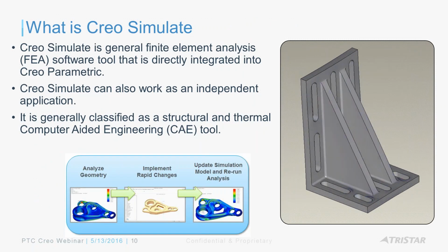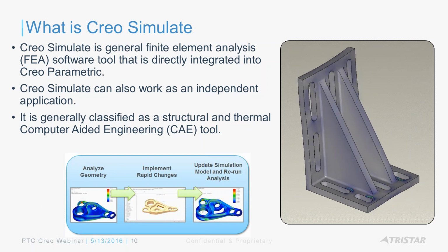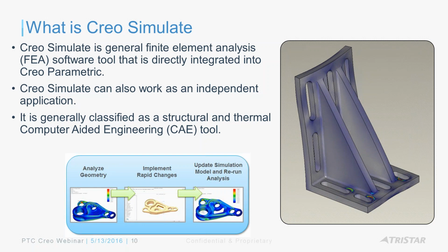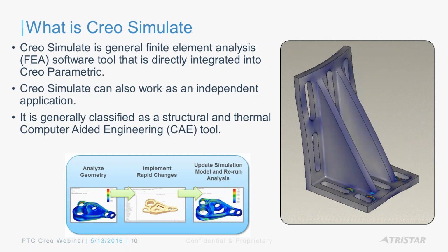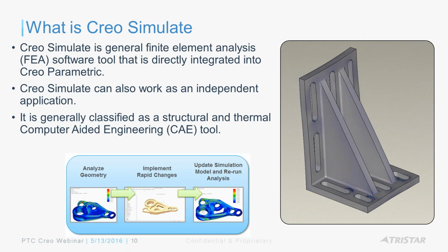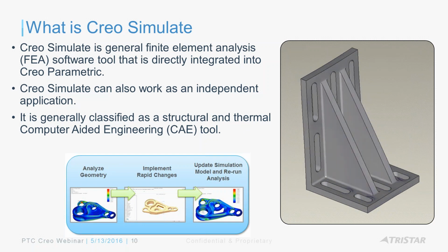Now, if I were to take the first one, which is obviously Creo Simulate, many of you may have used it or are currently using it. It's the structural and thermal simulation tool within Creo Parametric. It can work independently of Creo, or it can work in integrated mode with Creo. And the good thing is you're not just simply analyzing for stresses and deformations and frequencies and temperature.